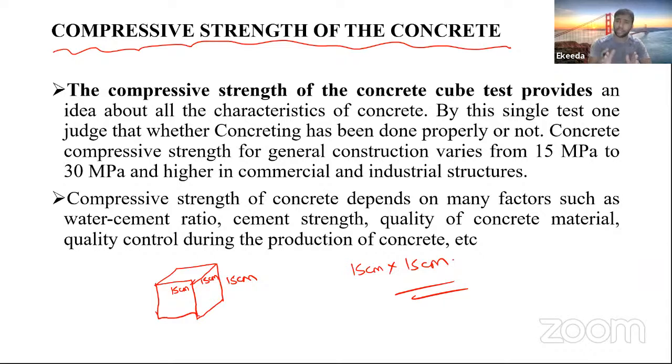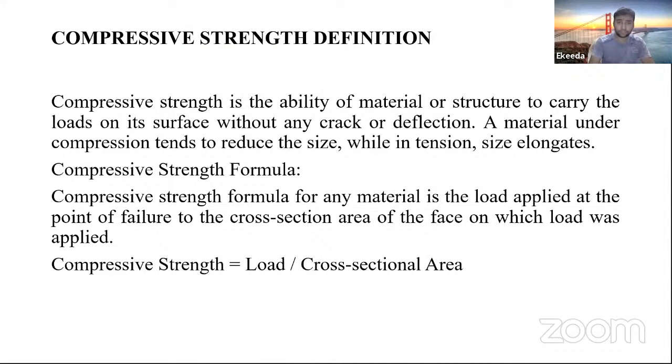At that load at which the concrete fails, we will record that reading and divide that load by the surface area, that is 15 centimeter into 15 centimeter, and we will get the compressive strength of that concrete. Is it or not?